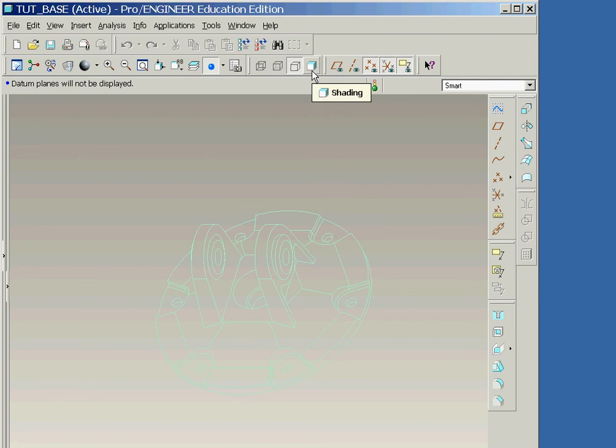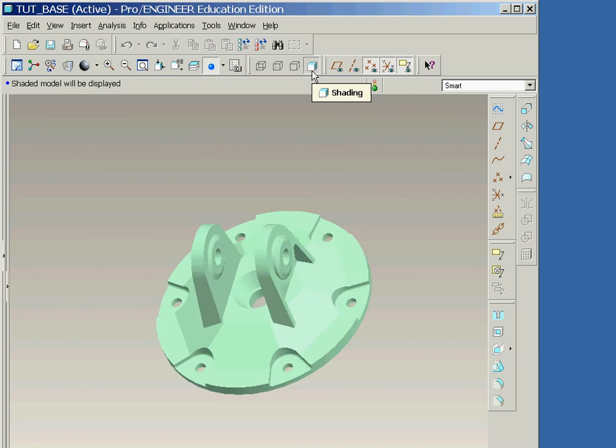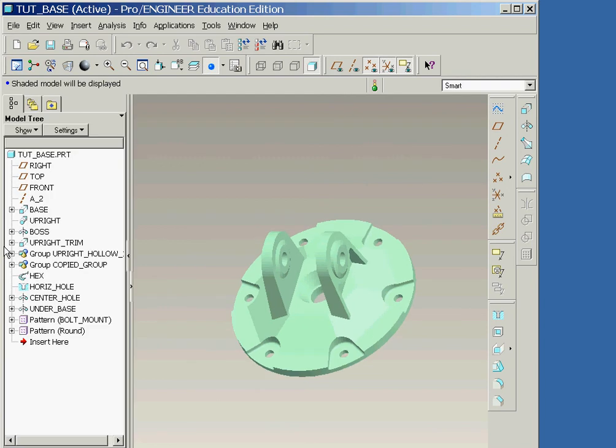As we will find in the subsequent lessons, the creation of parts in Pro E is accomplished by constructing a series of features. The list of features used to create a part is displayed in the model tree, which we'll open now, by opening the Navigator pane and making sure that the Model Tree tab is selected. As you can see, as we click on a feature in the graphics window, the feature's name is highlighted in the Model Tree window. We can also click on a feature's name in the model tree and see the corresponding geometry highlight in the graphics window.